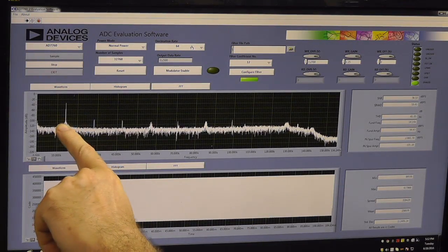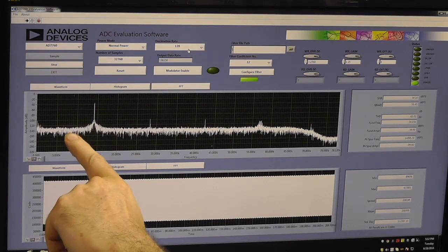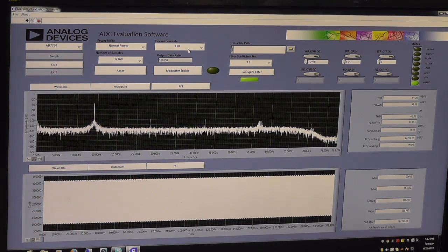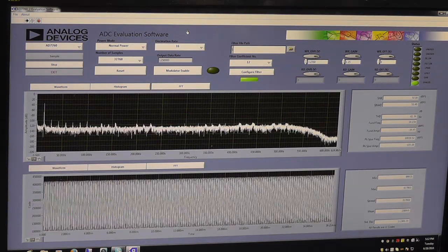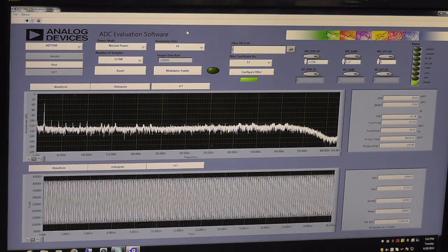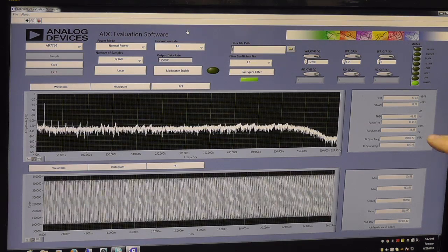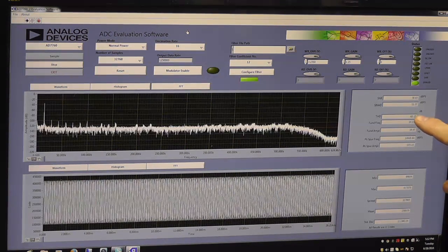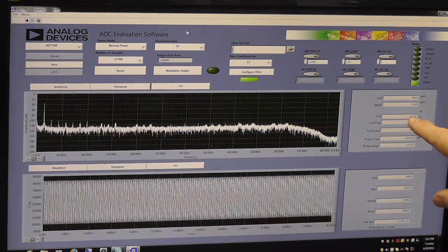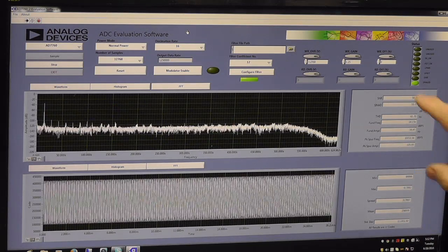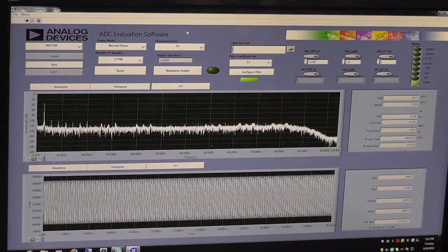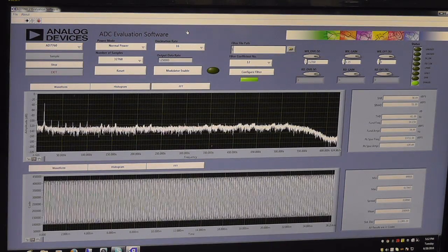Now, if you do it without really taking care of your data, you end up changing the frequency you think you're spotting if you decimate at an improper rate. And so that's one thing cool about this. I know the frequency I'm putting into it, so I set it back, and there's my correct value. So kind of an interesting display. If you were researching or using this part, it's very interesting because it gives you the actual total harmonic distortion, the signal to noise ratio, spurious frequency, everything is spelled out for you as measured. So it actually is very good if you're doing this for real and not 2 minutes in a video.